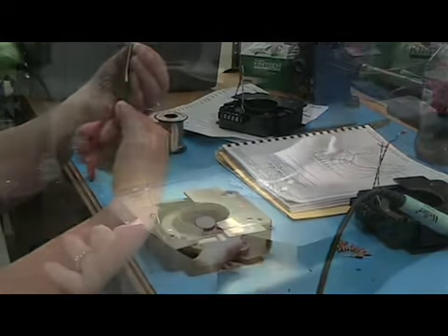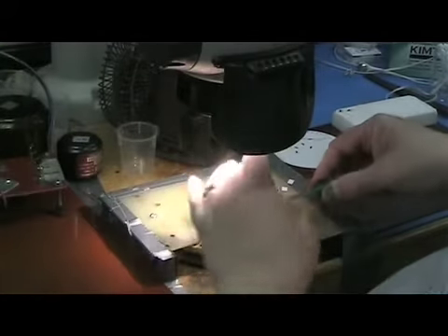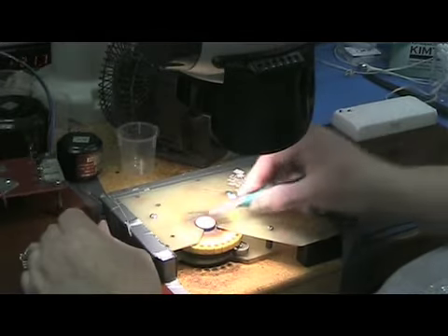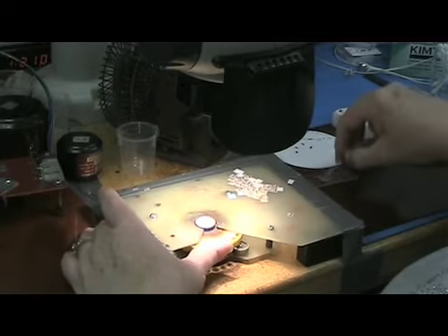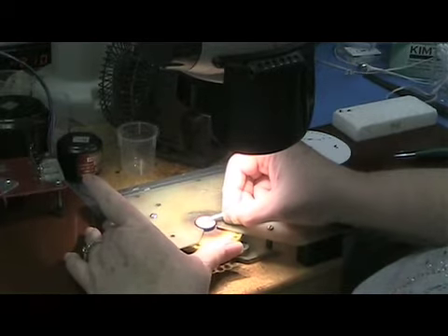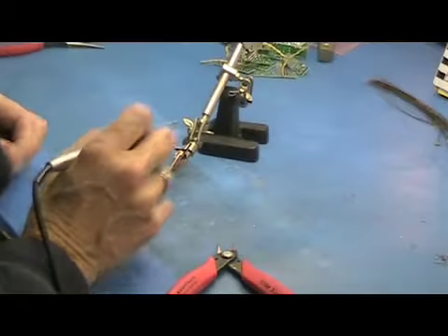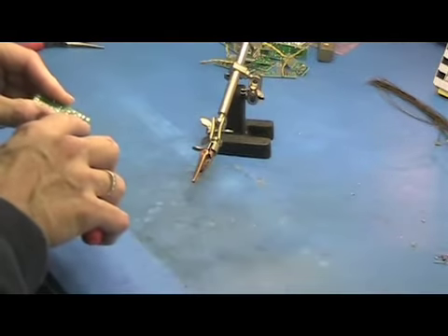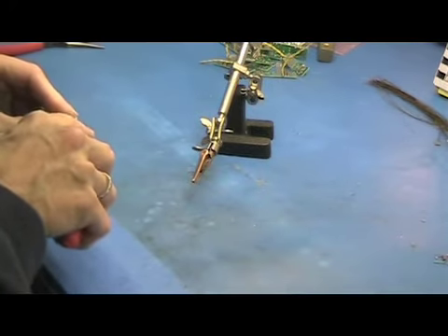Also, the Hall effect is all low voltage operation, well below the 24 volt safety level that we normally think of. So non-contact, simple to install, measures DC, and complete isolation are all good reasons to use Hall generators.